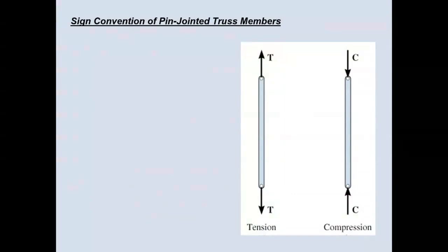All right, so that is when you have a bar member in tension, that is the axis of the member. What is the axis of a member? You connect from one end to the other end, that is the axis. When I say the member is being loaded axially, it means the loads are collinear and coincide with the axis of the part. Whether they are pulling this apart, which makes it longer, or pushing these toward each other, which makes it shorter, either of these two scenarios would happen for every individual member inside a truss structure.